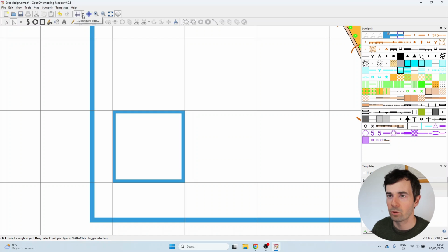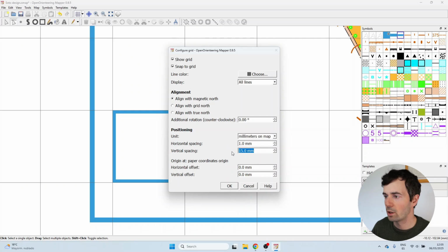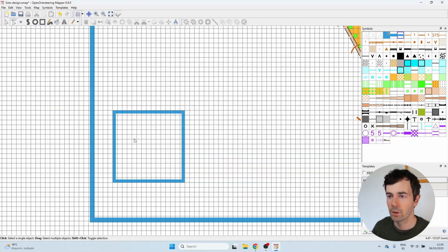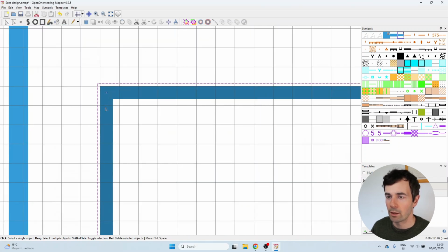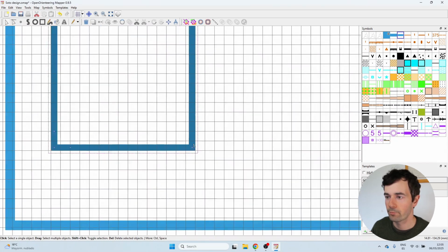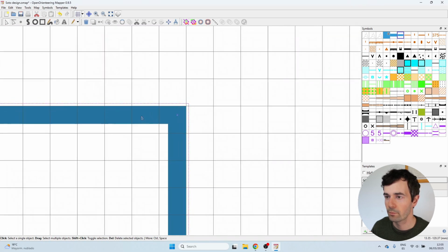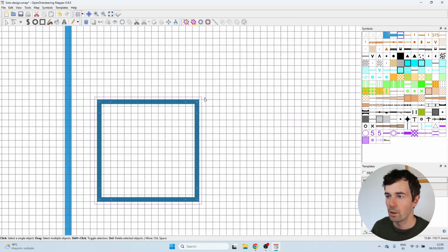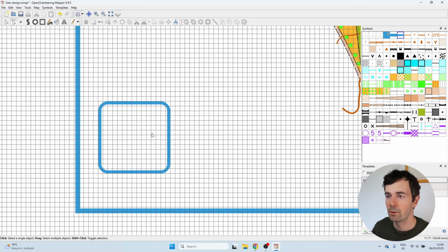So what I want to do is just change the frequency of the lines in my grid all the way down to 1 millimeter. And then I can just come in and I want to add a point around this corner point. So I'm going to move down 2 lines, and on the second line, create a new point. Here again, create a new point. And I'm going to do that all the way around the square. And then I'm going to get rid of the corner points, switch to line mode with L, and then control and click on these corner edges. And we get this nice rounded box.